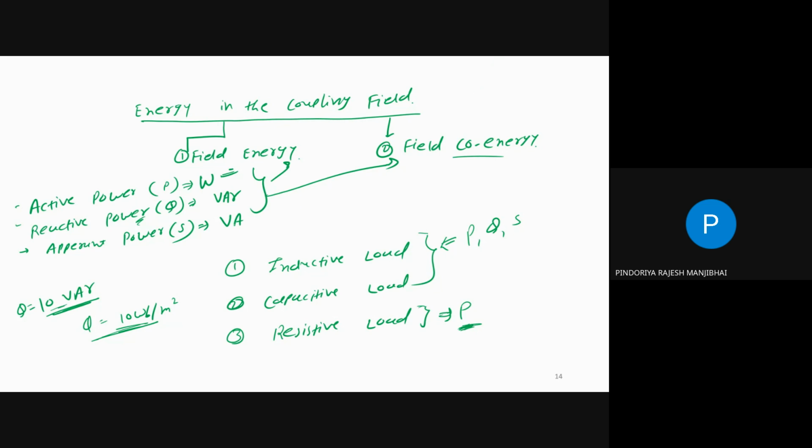One more thing for more clarity. Transformer, right? What is the unit of a transformer? VA, correct? And what is the unit of a motor? Kilowatt. Yes, kilowatt, otherwise watt, correct? We put the K because of the high rating; otherwise the normal unit is the watt. Why is the transformer unit VA and the motor rating kW? Again, this concept is related to co-energy and reactive power.